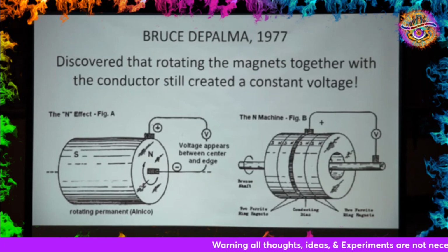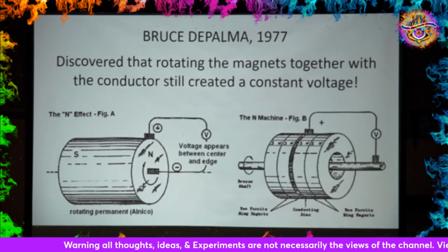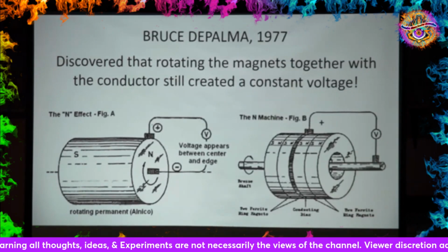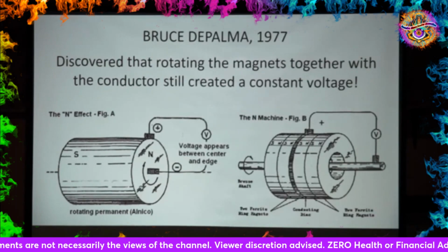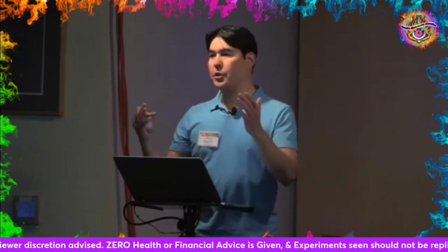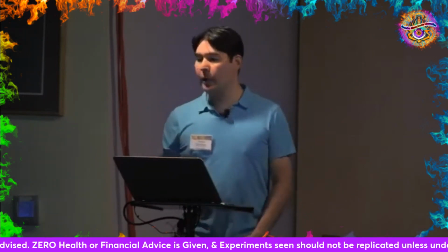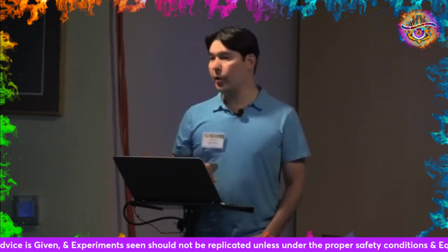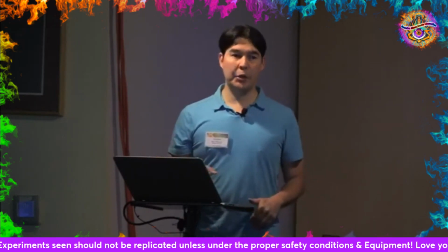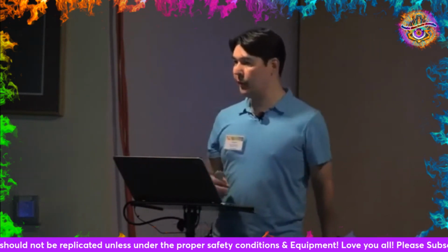What's even more interesting is that it's a very, very small voltage. It's almost pretty much unusable in most people's experiments. They're lucky to get millivolts spinning a magnet like this at a couple thousand RPM. But what they find is that it proportionally creates a massive amount of current. And so they've actually made a lot of commercial homopolar generators for low voltage, high current applications, such as welding.